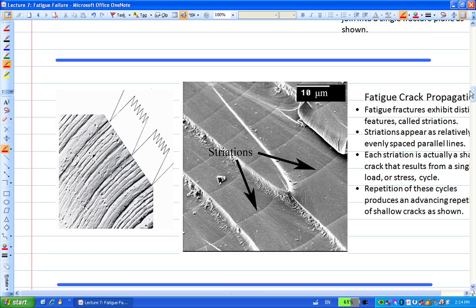And this diagram shows you the so-called crack propagation process. So you see all these marks here, those patterns. This is what we call striations. Okay, striations. Each striation, each wave right here, is due to one cycle of this stress. Your loading may not be as beautiful as a sinusoidal curve, right? Maybe it's pretty noisy like this. That essentially will give you a different look or different patterns of this striation set here.